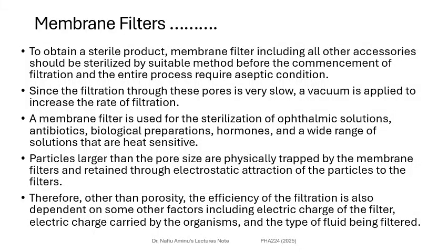Particles larger than the pore size are physically trapped, as I explained before, and those that are sufficiently small can permeate through. In addition to that physical way of retaining the bacteria, electrostatic attraction also takes place. So electrostatic attraction of particles can occur on the filter. Other than the porosity, the efficiency of the filtration is also dependent on other factors, which include the electric charge of the filter. Some filter media have certain charges which also play a very vital role in retaining the microorganism cells and preventing them from passing through.